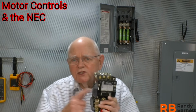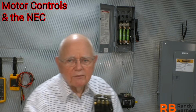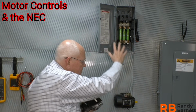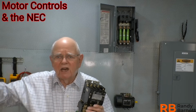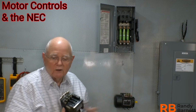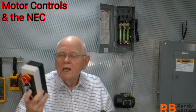Well, in order to supply that coil of wire, I'm going to use my control circuit, not the main power circuit. Two separate circuits. We brought power from the fuses on down through the motor starter, down into the motor runs, that's fine, but how do I control it? That's an entirely separate circuit. This could be a 460 volt three-phase motor. My control circuit could be 24 volts AC or DC, 120 volts AC, 125 volts DC, whatever it is.